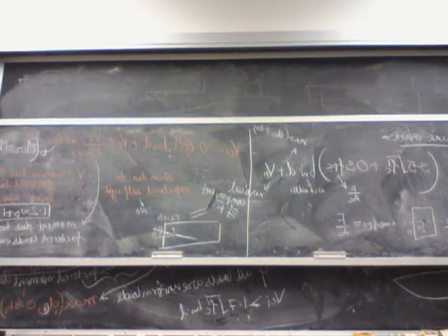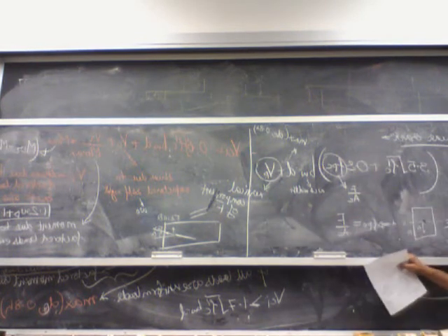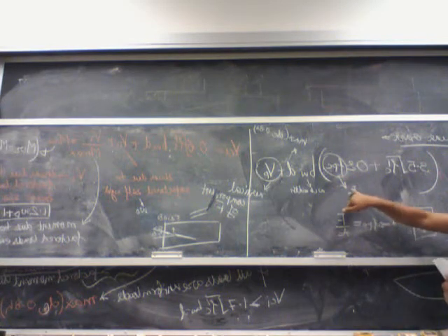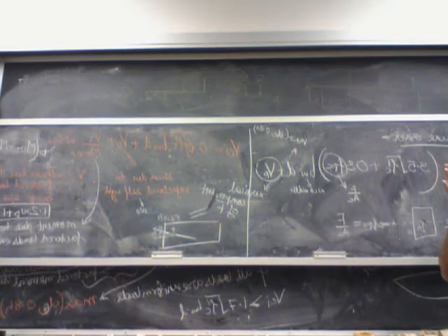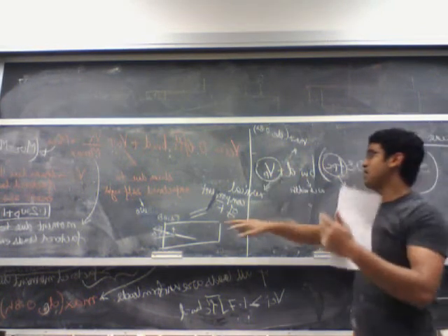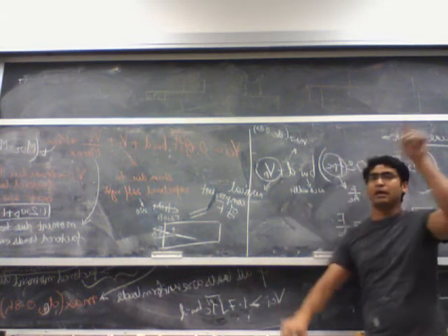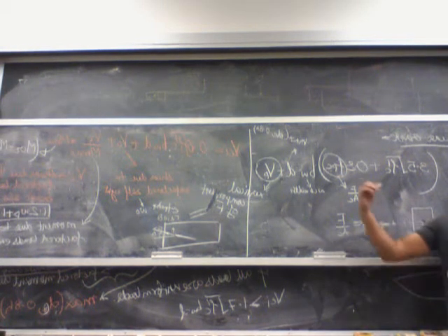Now the thing we talked about, the development length, comes into play in this term and in this term. Because if I go near the supports, my actual F in my strand is not FPE times AP, because it has to increase from 0 to FPE over a distance of LD. So within that distance, your FPC is not simply F over AC. It's less than F over AC, because the actual force within that length is less than FPE times AP. And the same thing is true for VP. Within that length, this F is less than FPE times AP. So you have to account for the development length within that length of LD. That's where the development length comes into play in the shear design.